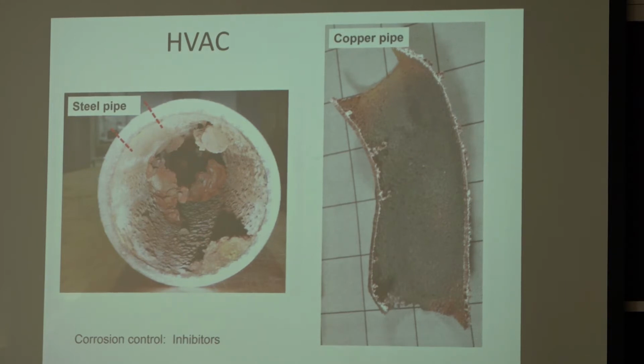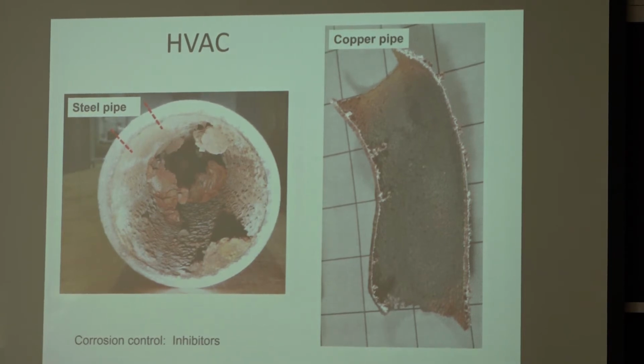And for the image to the left about the steel, again, with different flow rates during service, you can minimize the risk of forming these tubercles. So you can keep the composition more homogeneous if you are above a certain speed. So now maybe you're not as interested to design a plumbing system because you have a minimum and a maximum, right? So you really are having to do your homework based on experience of similar use as to what is acceptable to control corrosion. You cannot eliminate it. As soon as you take that piece of copper and put water in it, there are reactions taking place. You just need to make sure that they don't affect the service life, if you can.